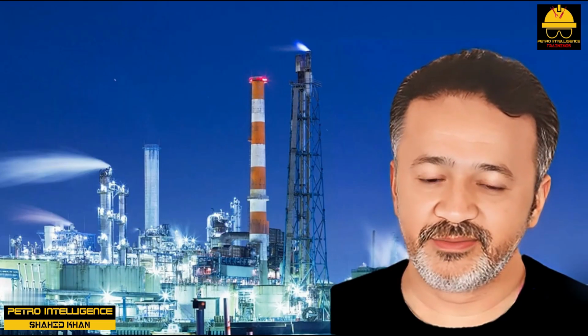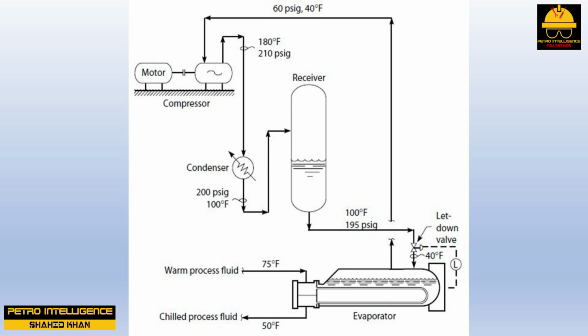Suction throttling. Suction throttling is the preferred method, as shown in the picture. Suction throttling also wastes energy. Whenever a control valve is partially closed in any service, energy is always wasted. But with a fixed-speed centrifugal compressor, it is still the best option. As the suction valve is closed, two things happen. The flow of refrigerant vapor to the compressor is reduced, and the compressor's suction pressure drops.